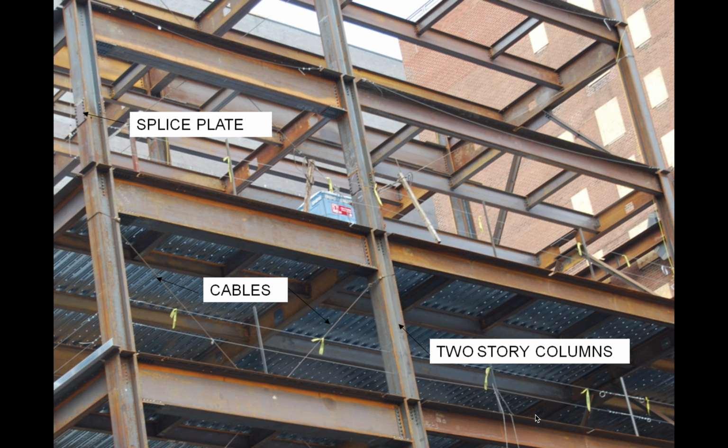That gives you an 8-foot ceiling in each floor, but it's also a very convenient weight to put on a trailer and deliver, and not only fabricate, but then put on a trailer and deliver. You could really go up to about 40 feet length or longer, but that's the typical. It's just easier to handle on the site, and it reduces the amount of splices if you can at least get 2 stories per column.